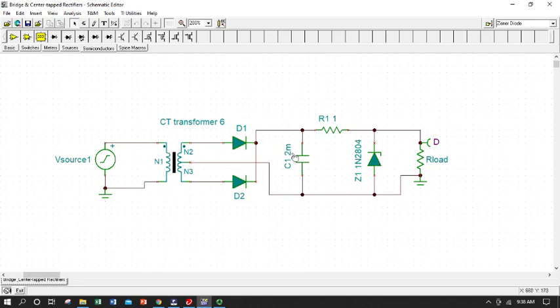So we'll just take a moment right here to step back through all the things that we're doing to give ourselves that nice DC with only a little ripple, looking at the different stages of our power supply. So we've got a certain periodic, we'll call it sinusoidal, signal, it's probably coming from the grid. So we have some kind of sinusoidal voltage signal coming in maybe from the wall. We use a transformer to adjust its level, but it's still a positive, negative, periodic sinusoidal signal.